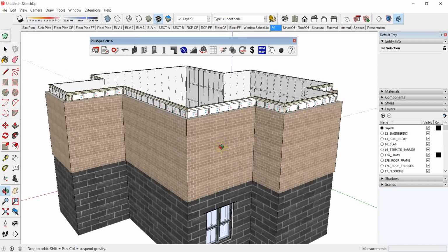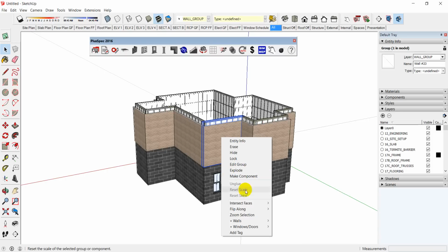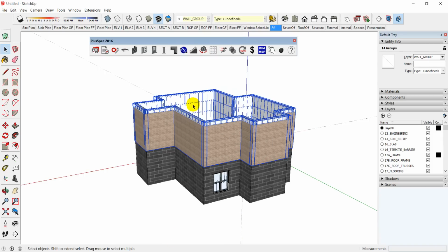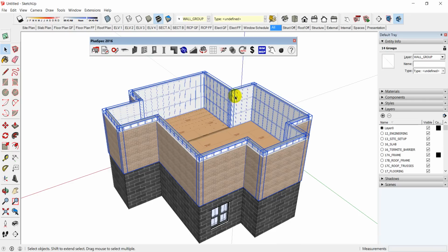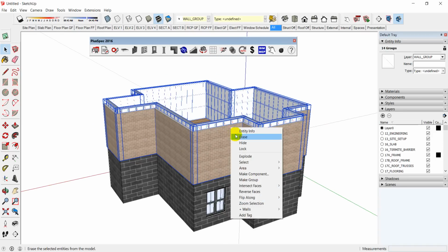Okay, so the best thing when all walls are joined together, so if I clicked here and went right click, select connector walls, and I can select the connector walls. It's actually sitting down below the screen there, guys. Right, you notice that all the walls are joined together. If you're using different construction methods, you might need to join them together. I can also right click and walls, and I can create a face from the walls, or I could do it manually if I wanted to.